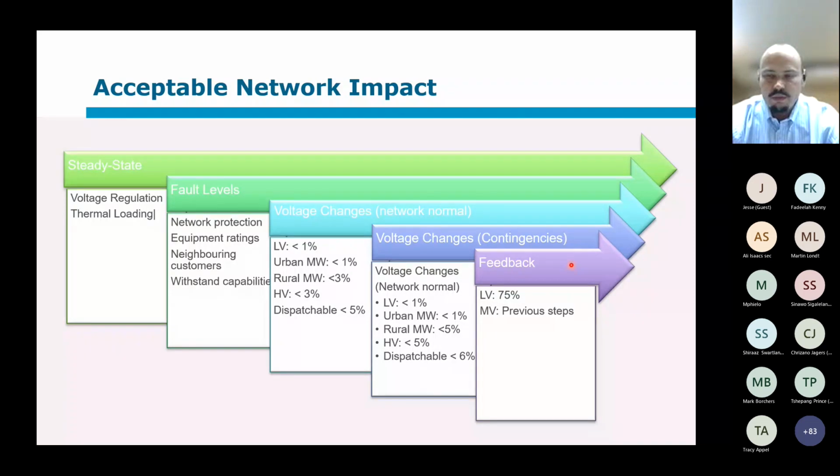And this can cause damage to the transformers, so we never want to take it up to full capacity. That is based on some discussions also with the Eskom transformer manufacturers, and I think municipalities use very similar transformer specs because that's also NRS and SABS specifications, as well as limiting the impact of harmonics.